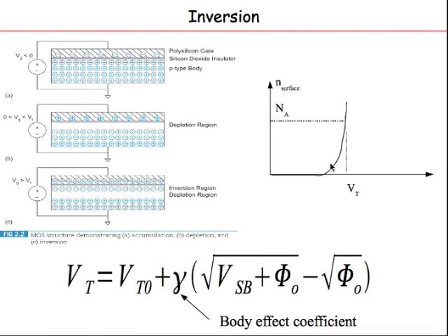It is the same curve you would have seen in the diode current, I versus V, a hockey stick curve. Of course, when you plot the log of the concentration of the electrons versus the gate voltage, it will look like a straight line, but if you plot in the linear scale, it will look like a hockey stick.